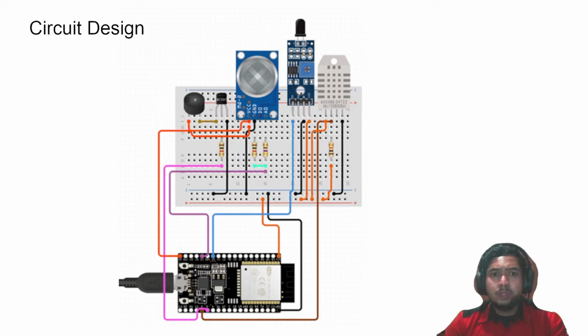This system will also use small electronic components such as a transistor. The transistor is used to amplify the power to the buzzer, and a diode is used to provide a safe path for the inductive current when the buzzer is off so that the voltage does not rise and damage the circuit.